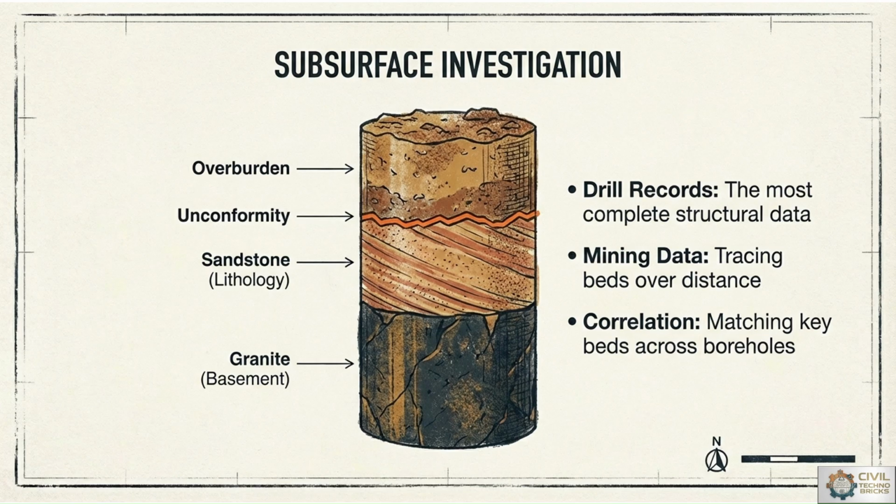With reference to flat terrain, it is easier for highway construction but may face drainage and flooding problems. Remote sensing and GIS techniques are used for terrain evaluation and route planning, where proper terrain assessment ensures a safe and economical highway alignment, which is based on subsurface investigations.